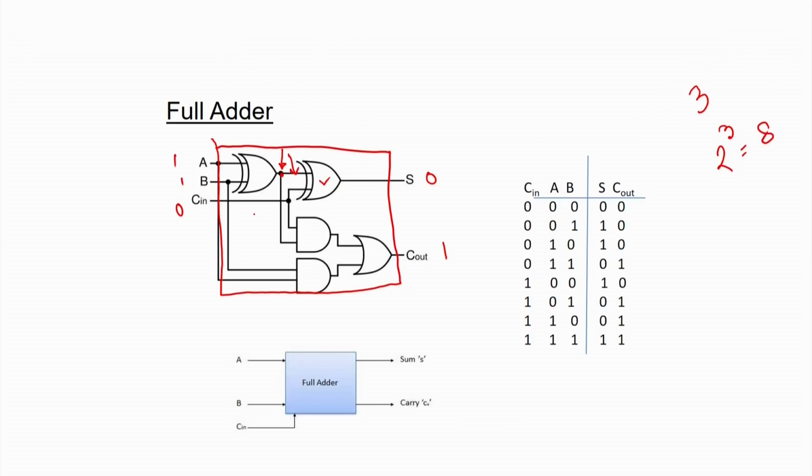So, finally, we are going to get a correct result. This time we have to consider that the final output we are going to get after some amount of time once we give the stable input, and this time depends on the propagation delay of the components of that gate. That means to get the result of a full adder, it is going to take some time. We have to consider that particular time also.